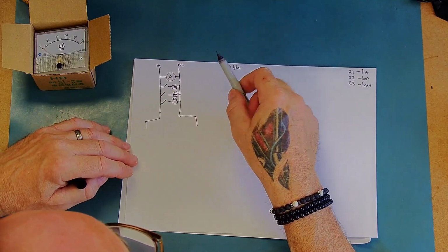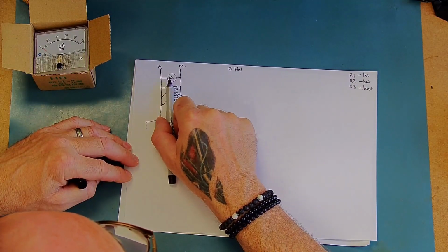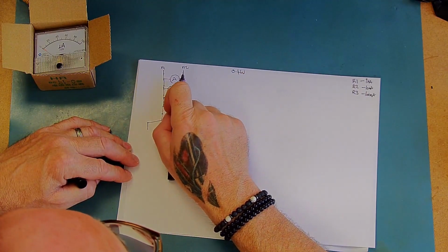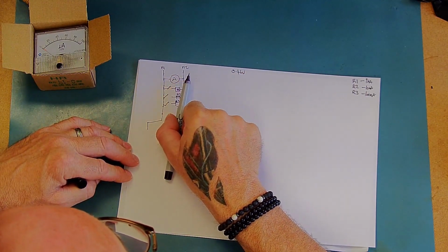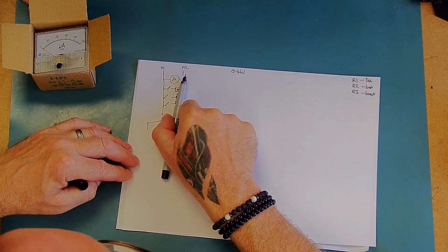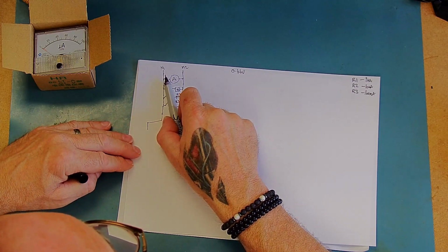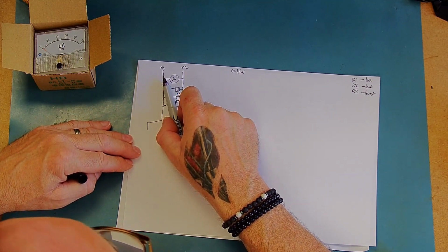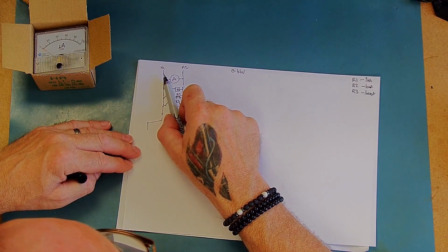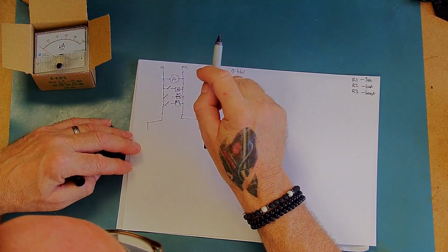So if we can actually read the voltage across the meter itself, we can say that if it goes up to 0.46 on any given range, then it's at the maximum of the range. By the same token, if it goes down to, let's say, 0 or just over 0, we know it's at the bottom end of the range, and therefore we should be able to go up a range.